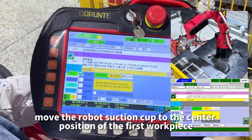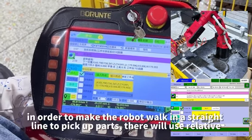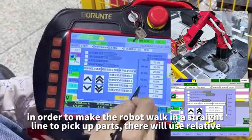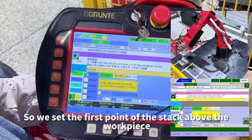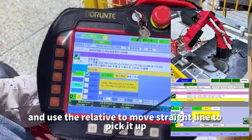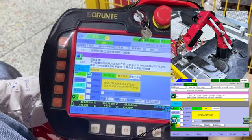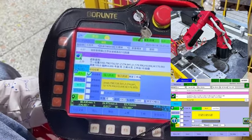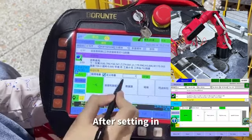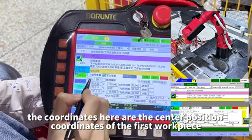Move the robot suction cup to the center position of the first workpiece. In order to make the robot walk in a straight line to pick up parts, we will use relative. So we set the first point of the stack above the workpiece and use the relative to move in a straight line to pick it up. After setting it, the coordinates here are the center position coordinates of the first workpiece.